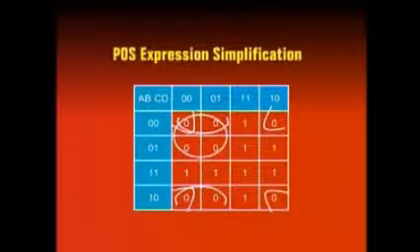An appropriate way to implement the adjacent ones detector circuit is to simplify the product of sum Boolean expression represented by the function table, and then from the simplified Boolean expression the circuit can be implemented. The circuit of course would be simpler as compared to the standard product of sum based expression. The function table information is directly mapped to a 4 variable Karnaugh map. The zeros are grouped together forming 3 sum terms. The 3 terms are a plus c, b plus c, and b plus d.